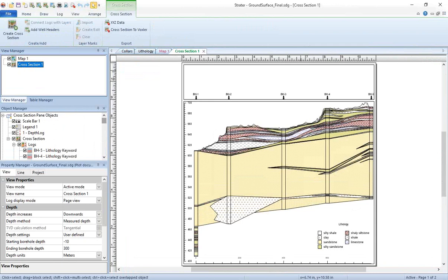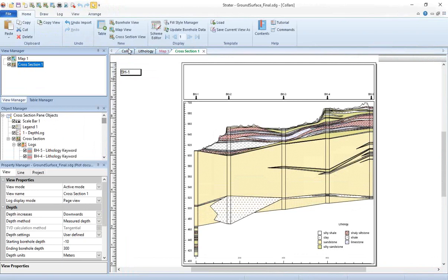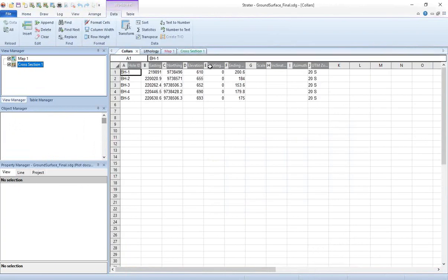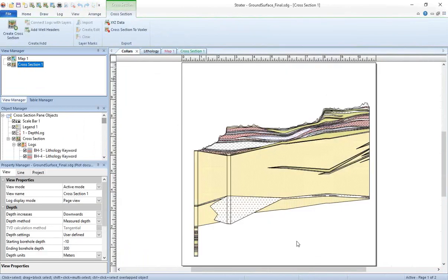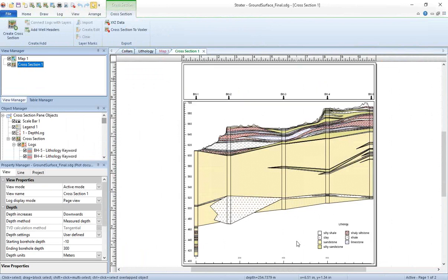All right, so one of the questions I have is, how did I make this surface inside of Surfer? I did mention that. What I did is I had a gridded XYZ grid file that I created a contour map from, just the tops. I made a real simple grid file and then a cross section, and I used the profile tool to create the profile, and then I just exported it.